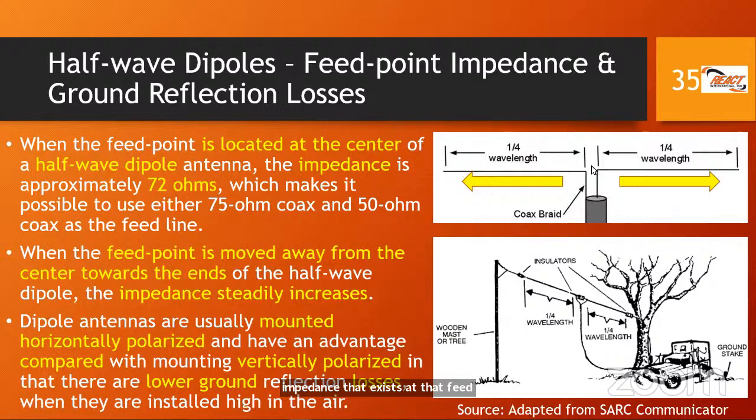For a half-wave dipole, the feed point impedance is actually not 50 ohms, but somewhere in the vicinity of about 72 ohms. Remember we said we are trying to make antennas where the feed point is 50 ohms, because we are typically using 50 ohm coaxial cable, and typically our transceivers have an output impedance of 50 ohms. Hams are matchmakers and we try to match that. But the reality is life is not always ideal. It's 72 ohms when we construct a dipole as is.